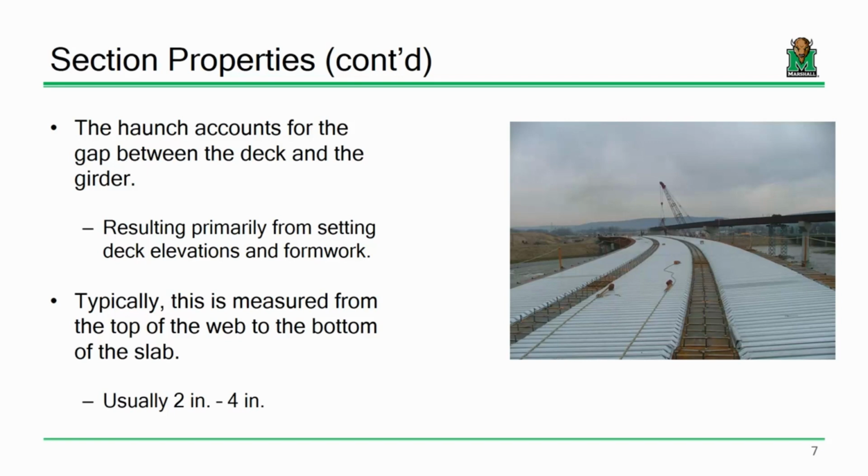Unlike buildings, and don't get me wrong, buildings see these types of forces as well, but in no way, shape, or form at the same magnitude. Bridges see a lot of cyclic loading. They're loaded, unloaded, loaded, unloaded. Trucks drive over and over and over again. And because of that, elements like shear studs and connections and those fabrication details can experience failure at really, really low stresses.